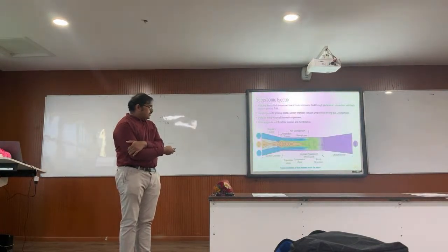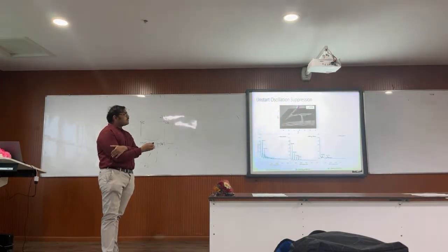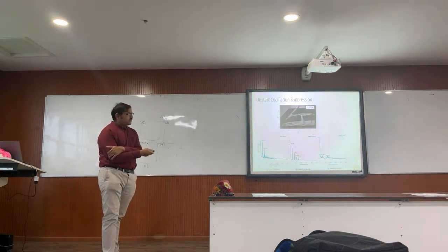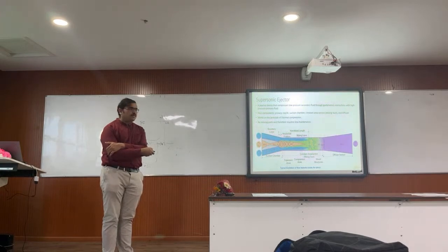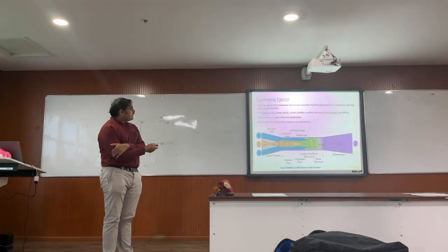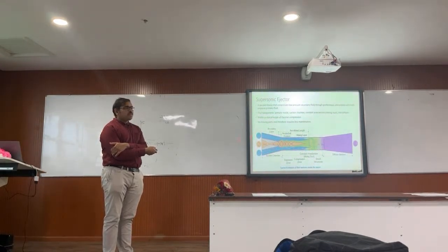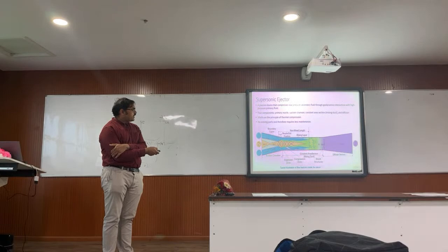Okay. Now coming, so this was a study on large amplitude oscillations in unstart of a hypersonic intake. We also observe very large oscillations when we have a device called a supersonic ejector. Now this is a passive device. It's used for compression, and in this there are again no moving parts. It's completely aerodynamically designed, and it uses a primary flow which will be of much higher momentum. The high momentum primary flow enters the secondary flow, mixes with it, and then finally compresses it.